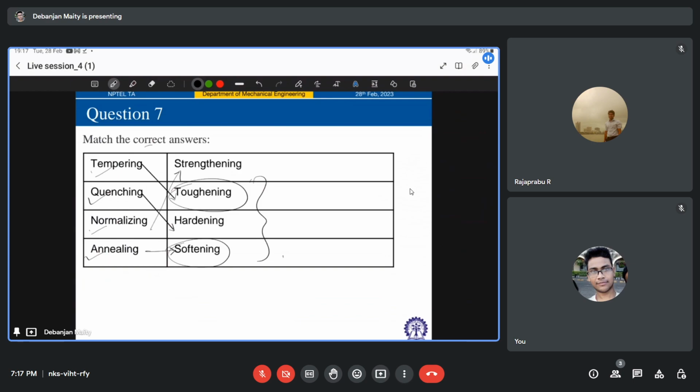So in tempering, I discussed martempering. Now there is another kind of tempering process which is called austempering. Austempering may be employed for certain grades of high strength steels which require a remarkable degree of toughness and ductility.